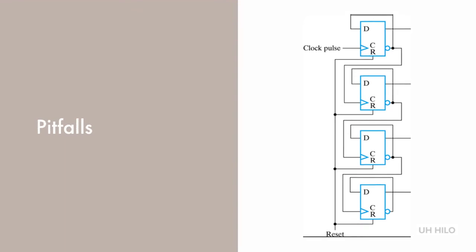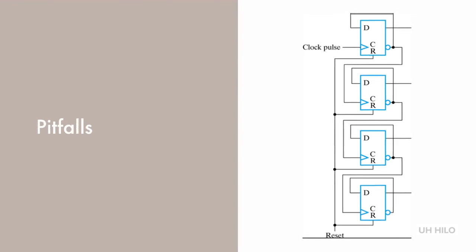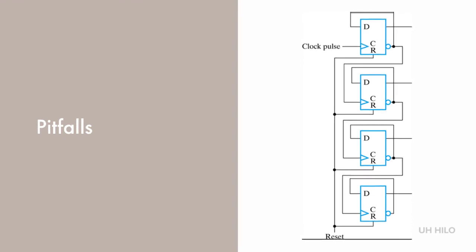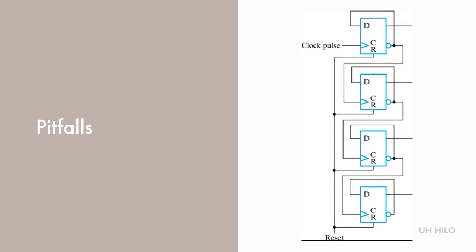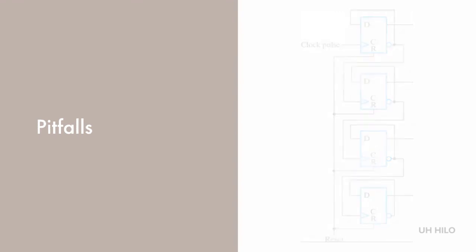Just because there's a clock does not mean the circuit is synchronous. For example, in a ripple counter, the clock drives at most one flip-flop clock input directly. All other clock inputs driving the flip-flops are actually state variables, so the changes in state variables that are outputs of these flip-flops are not synchronous with the clock. For a 16-bit ripple carry counter, the worst-case scenario is where all flip-flops change state, and the most significant bit changes 16 flip-flop delays after the clock edge of the first flip-flop.